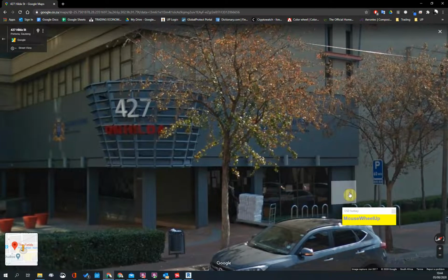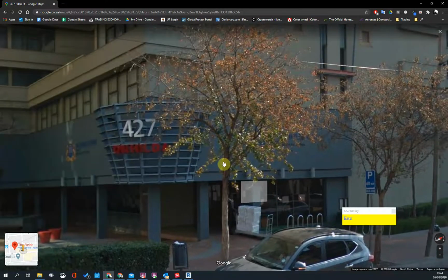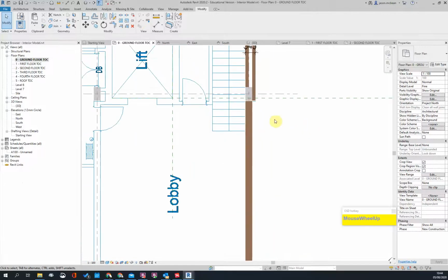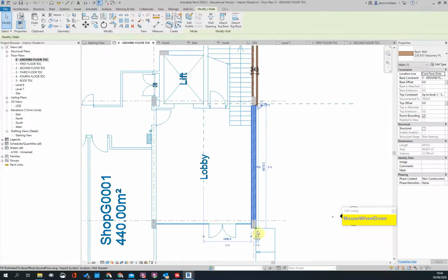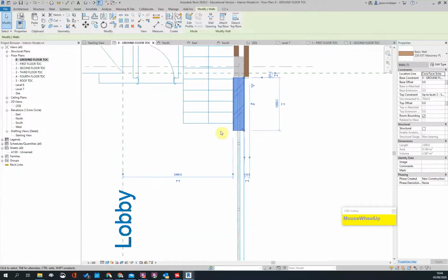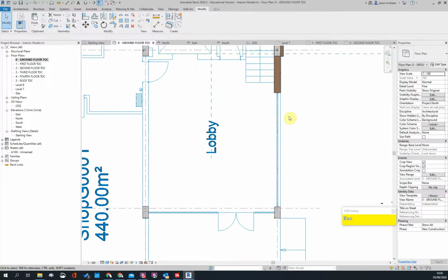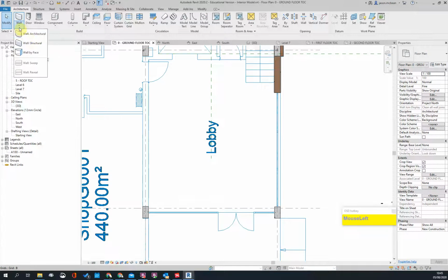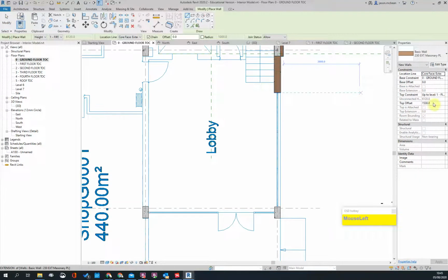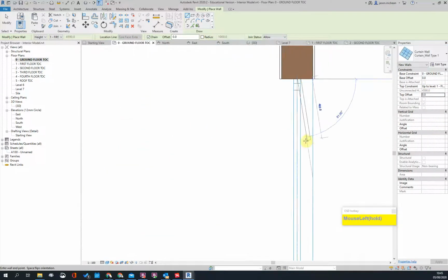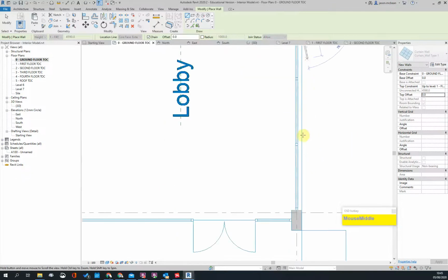So ground floor, okay, I'm going to get rid of that brick wall. I'm going to put in a, okay, so let's go to ground floor. I've got a feeling what they've done is, this is strictly not true where the shop front is. They've built in a second wall floor and now they've put a shop front. So here I'm going to go to architecture, walls, wall, and this will go to first floor. So from ground to first floor, 0, and this will be a stud wall.